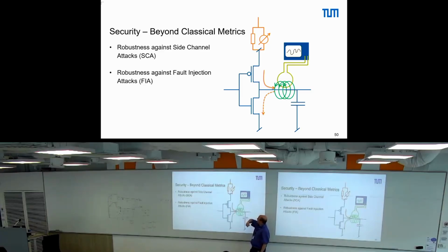The problem now is, if you implement in hardware some secure circuit, for instance, some AES circuit, I don't know if you have heard of this, that is there for encryption, then an attacker can observe this, and if your switching activity depends on your secret key, the attacker can derive the secret key from just observing the power consumption. This usually has to be done many times. You have to do a lot of measurements, perform hypotheses, and so on, so there's a lot of math behind that.